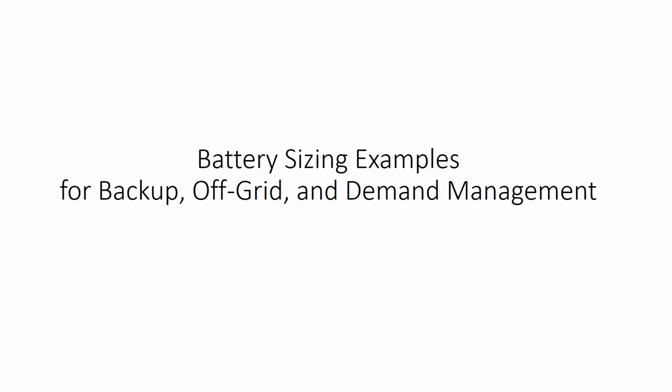So, let's see: battery DC negatively grounded, data center, communication center, whatever, battery positive DC grounded. What are your thoughts? I believe that you can ground the positive or the negative on a DC system, but generally the inverters are either floating or negatively grounded. So if it is a positively grounded battery, I think it will still work.